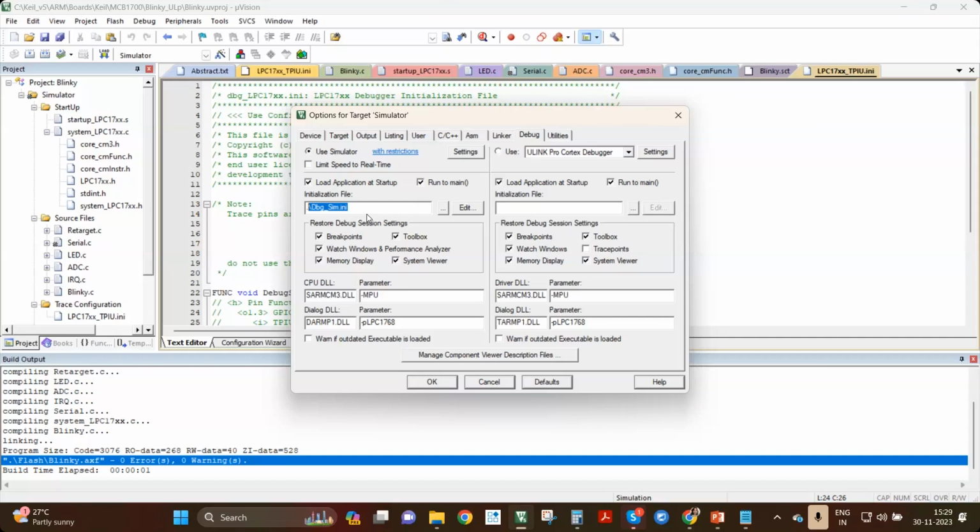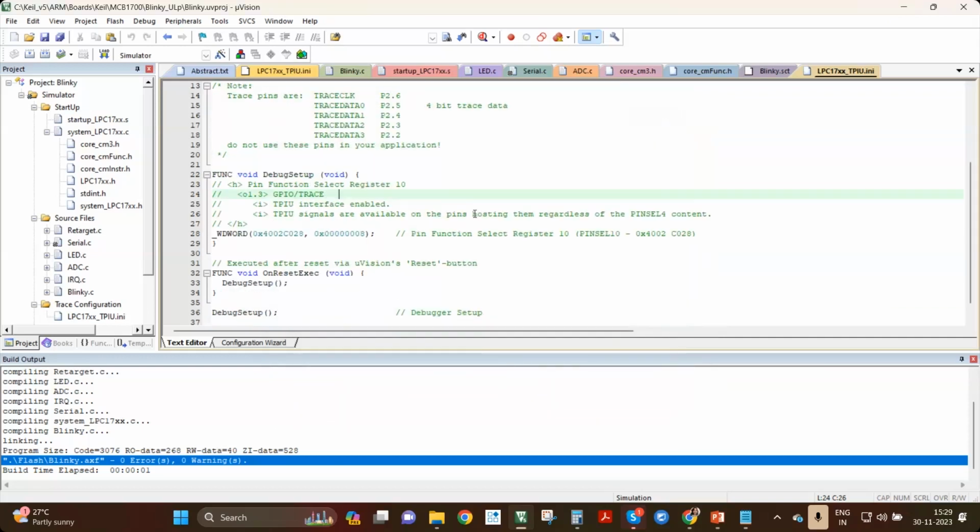And that potentiometer, as you know, is a variable input you can give, and it is connected to the ADC. So through this signal function, here we are trying to simulate the ADC peripheral. I'm using the signal function to generate the input. I was telling in the presentation that the signal function should not be part of your actual code, what you develop here.